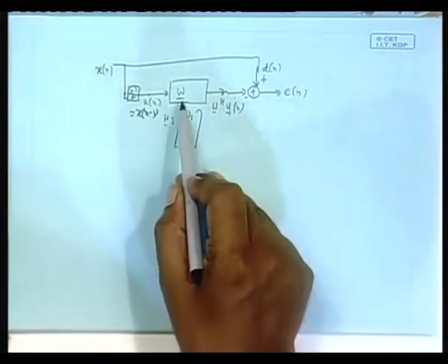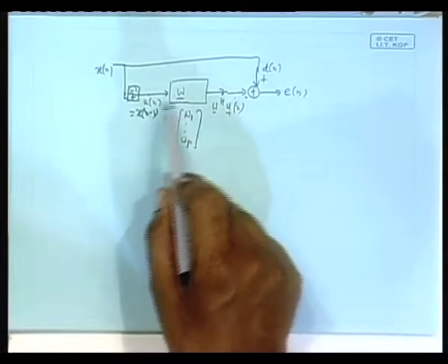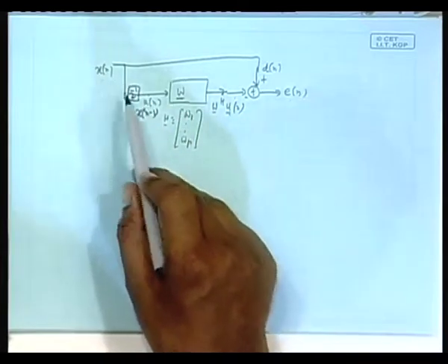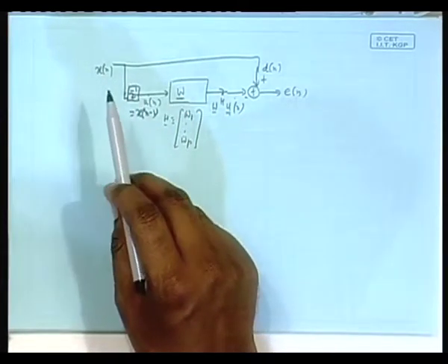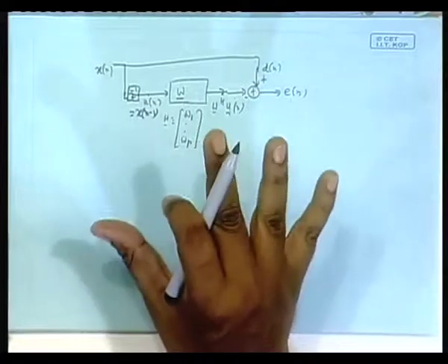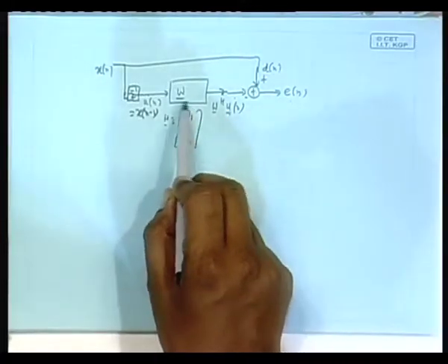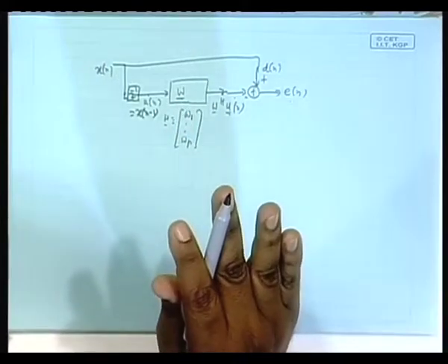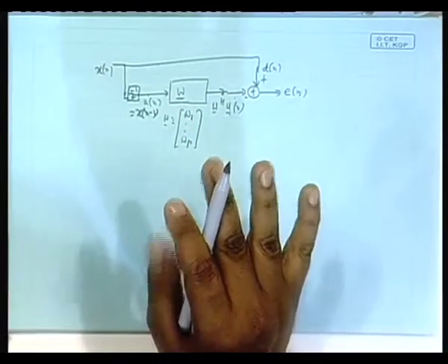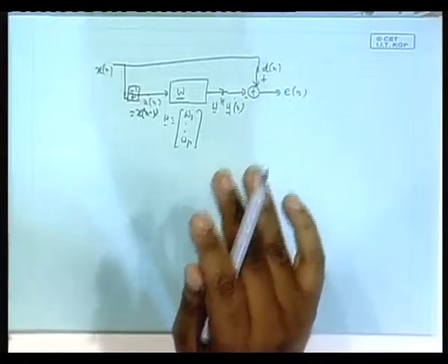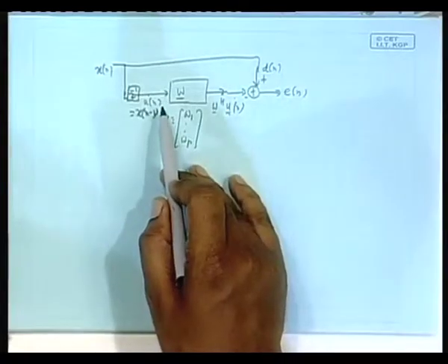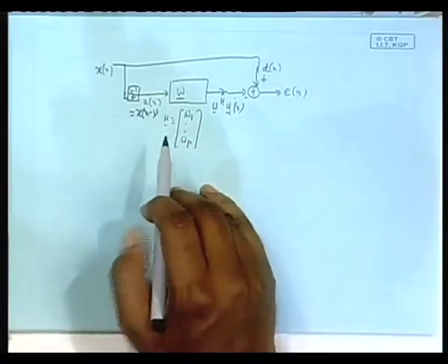In this case, obviously, the combiner coefficients follow from stationarity, if you assume x n to be wide-sense stationary. From our earlier analysis we know what this expression for W is: R inverse P. How are R and P independent of n? Because of stationarity.